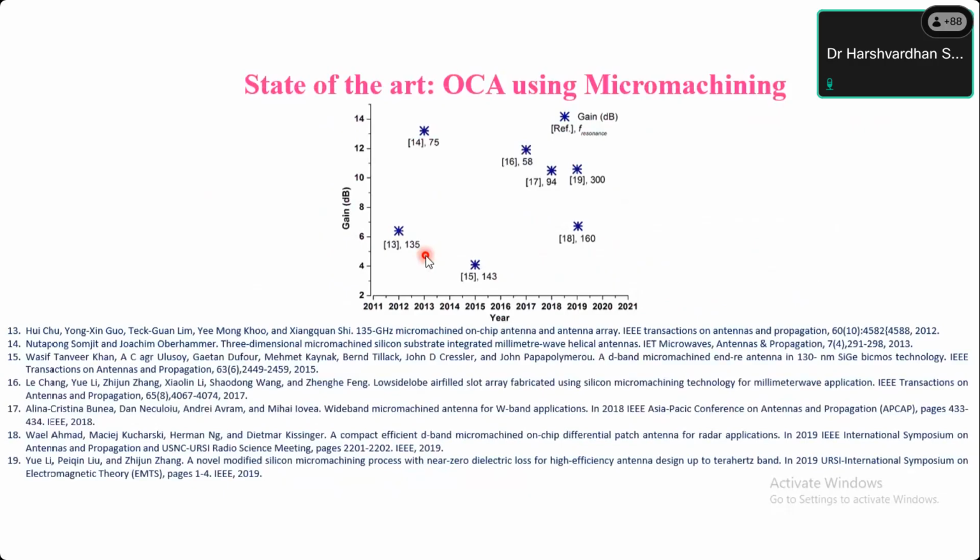We have worked on that also. We will show some models when we get there. So what we'll do is remove the extra, unwanted part of the wafer below the antenna. So what will happen, instead of getting epsilon of 11.9, which is exactly for silicon, now it is an effective epsilon with air and silicon. Okay, so anyhow it is going to be less compared to only silicon.